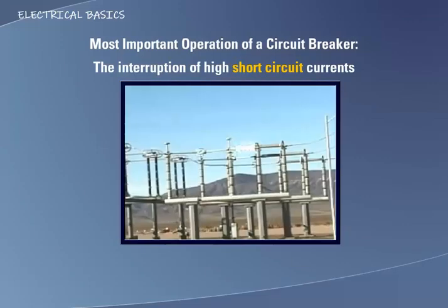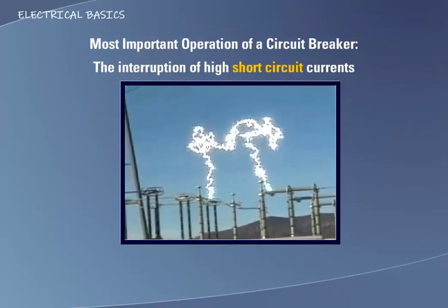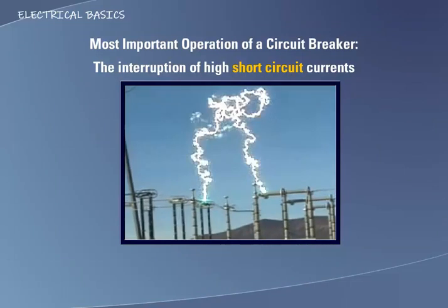For example, the amount of energy dissipated per phase by a 3-cycle breaker interrupting 10 kiloamps of short-circuit current is almost equivalent to stopping 100,000 kilograms moving at a speed of 36 kilometers per hour in approximately 50 milliseconds.